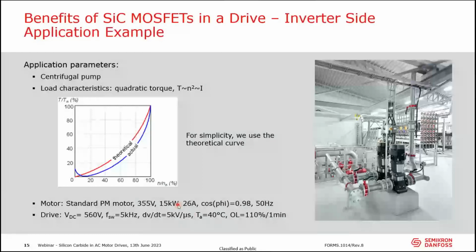Then typically an 11 kilowatt drive that you find on the market has a current of roughly 24 amps. It's too small. That would be 11 kilowatt. A 15 kilowatt typically has 31 amps. It's a bit too large, but you have to choose it. Otherwise, you can't run the application, and that's how it would typically be done. And then for the overload, of course, you take 100% of this, make sure your drive can do it, and that's it. I'm not sure if that was the question, but I think that's good enough for the time being.